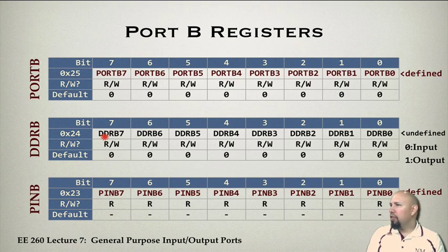Notice that I can't just read a specific pin number. I actually have to read the entire register and then extract the particular bit that I want. Whereas this PIN register actually reads what's on the pin. This is the register that's read whenever you input values. You can use this one, but this one is better to use because, remember, pins can change, and this is what's called the latched version of what's coming in on the pin, whereas these up here are not latched.